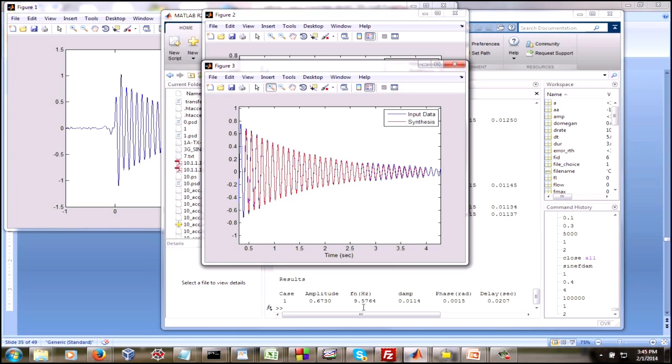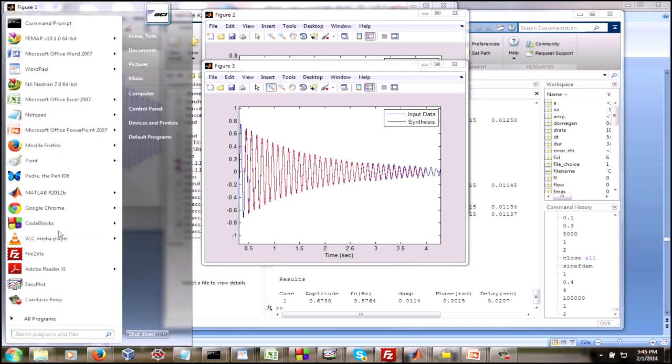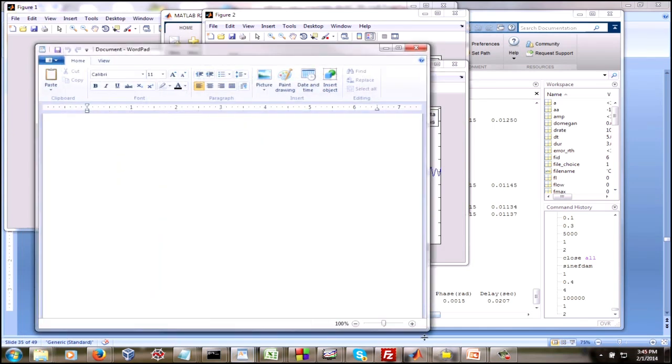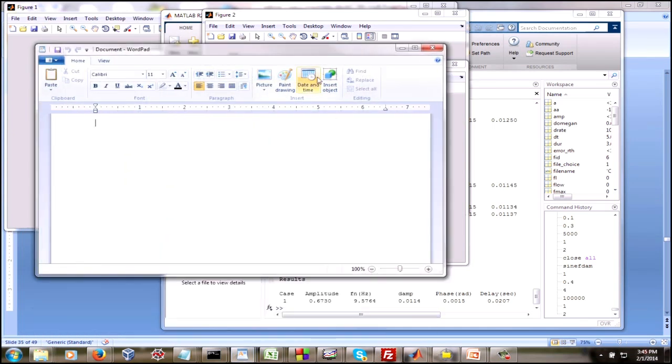So the guidance and control engineers in some cases have to go in and put in a notch filter or take other measures in order to have stable gains and phase margins and all those things that they concern themselves with. So as vibration engineers or structural dynamics engineers, we have an opportunity to interface with the guidance and control engineers.